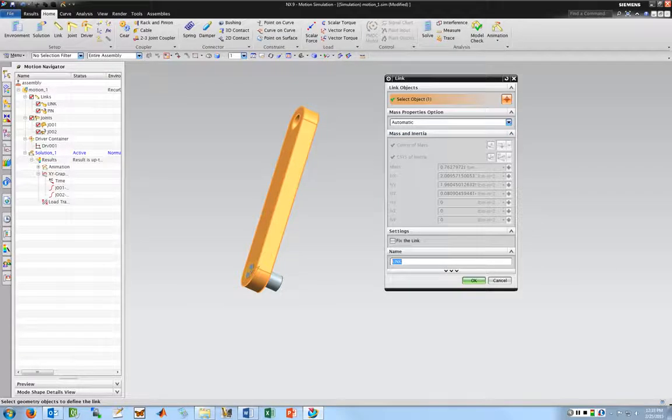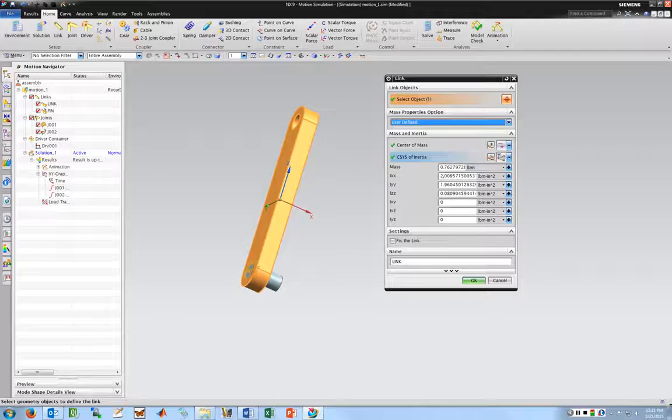Okay, so in the mass properties option, I could do user defined, so I can enter the mass and the inertia tensor here. One of the nice things about using CAD is you don't have to do this process. I believe you can set the density of the material somewhere, and it'll calculate it for you. If you basically just drew a rough approximation of the part, and it doesn't have the same mass properties, this is where you would enter the mass and inertia properties. So again, if you haven't had a dynamics class, you need to take a dynamics class.